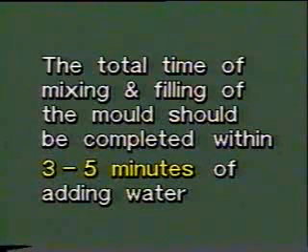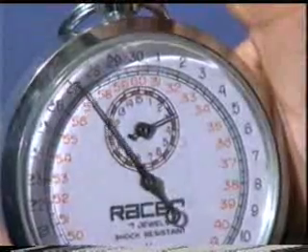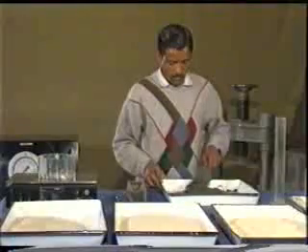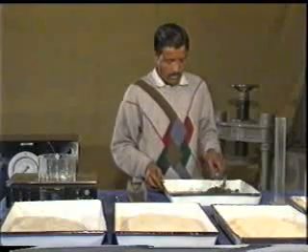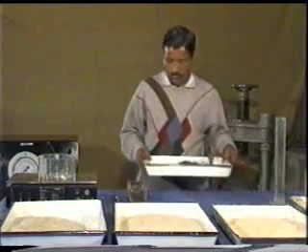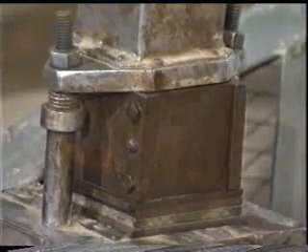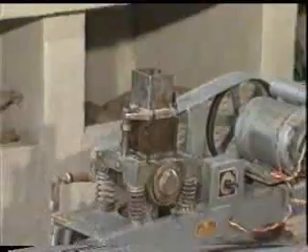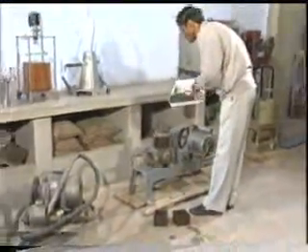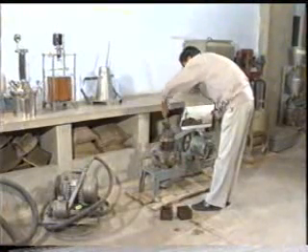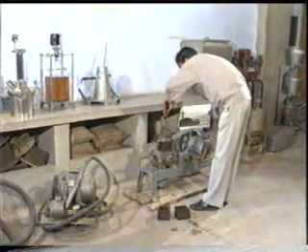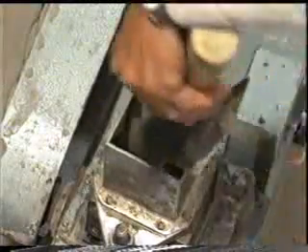The total time of mixing and filling of the mold should be completed within 3 to 5 minutes of adding the water. Place the mortar in the clamped mold through hopper on the top. Switch on the vibrating machine.